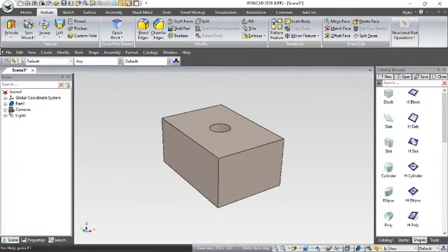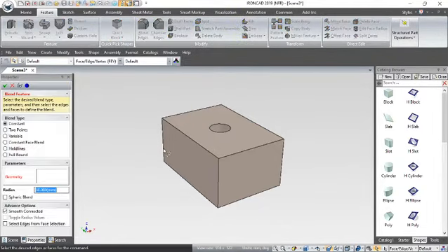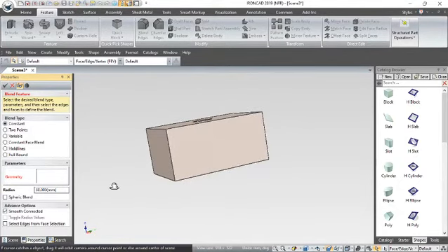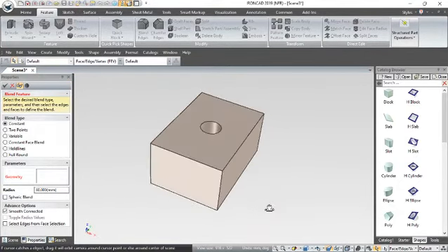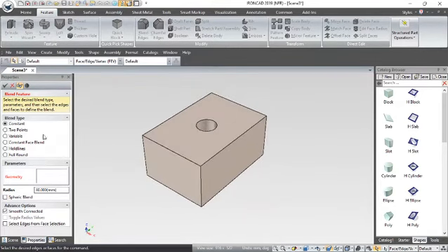So we go back now to this feature, and under the feature ribbon toolbar, there's one called blend edges. I'll pick that one, and by the way, if I press the mouse wheel down and keep it pressed and just move the mouse, you can rotate the part like so as well. In the properties box for this blend, you'll see we can set a radius here. So maybe I'll say I want that to be 35 like so.